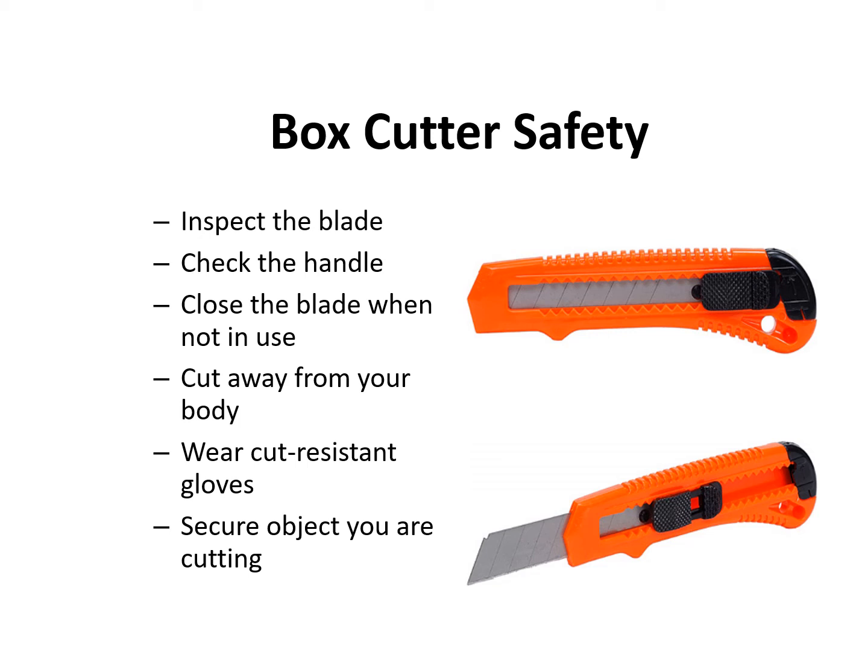Wear a cut-resistant glove on your offhand. Secure work with a vise or clamp. Do not hold the object with your other hand. Many box cutter related injuries occur when the box cutter slips and cuts the hand holding material being cut.